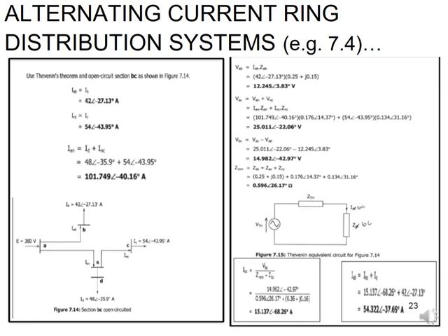So always use the opposite one of what you used when you did the conversion of your delta to your star. Here the opening line is BC. Why line BC at the top part? Because we always open the one furthest away from the source. So if you open that, you can see that your IAB is simply going to be the same as your IB, and then your INC, okay?